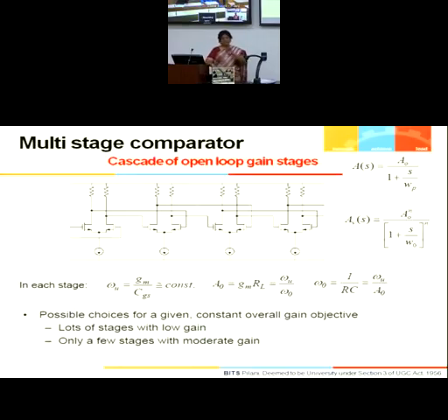Remember, whenever you have n such amplifiers in series, when you draw the frequency response of all of them on a single axis, they all affect each other, and the equivalent will have an omega naught which is decided by the omega naughts of all n stages. Similarly, zeros will also be because of the zeros of each stage. Poles will be because of the pole frequencies of each stage.